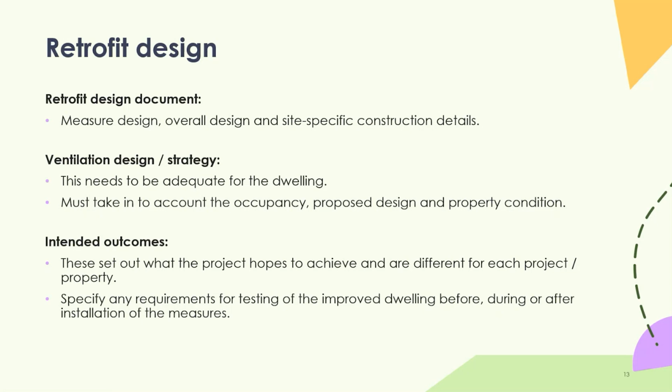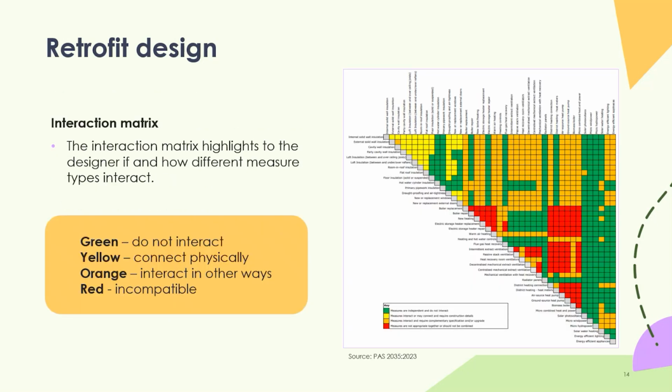So, to understand what the background draft or air permeability of those dwellings are. Again, with particular buildings, particular estates that might be built with a non-standard build type, maybe a timber frame or some other kind of non-standard design, they might have inherent issues around air permeability. So drafts because of construction design, and that might need to be very much incorporated in the retrofit design as well. Again, all these things need to be verified by the retrofit coordinator. We'll come onto that in a little while.